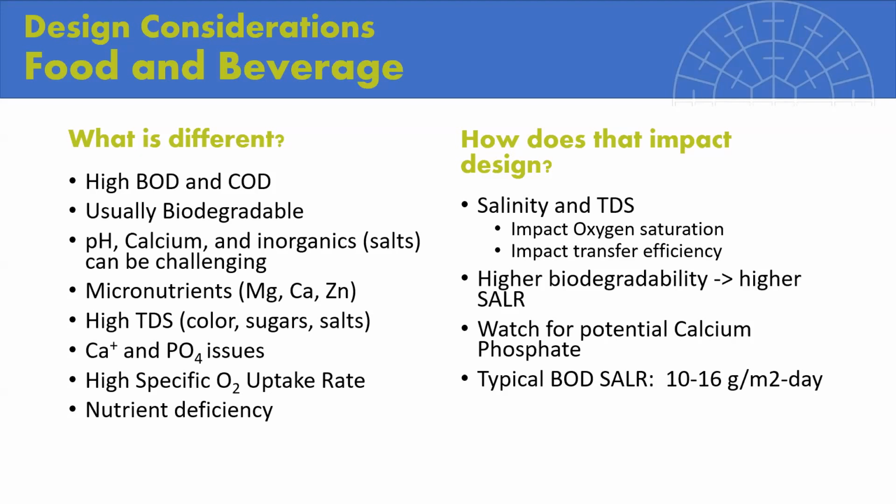So when you're talking about high BOD, high COD applications, and if you go back to the previous slide where we talked about slaughterhouses, a lot of times what we find is that we increase the mass of oxygen per mass of BOD removed. Therefore, we end up with a slightly larger aeration system. So that is going to drive the reactor area in a lot of cases.